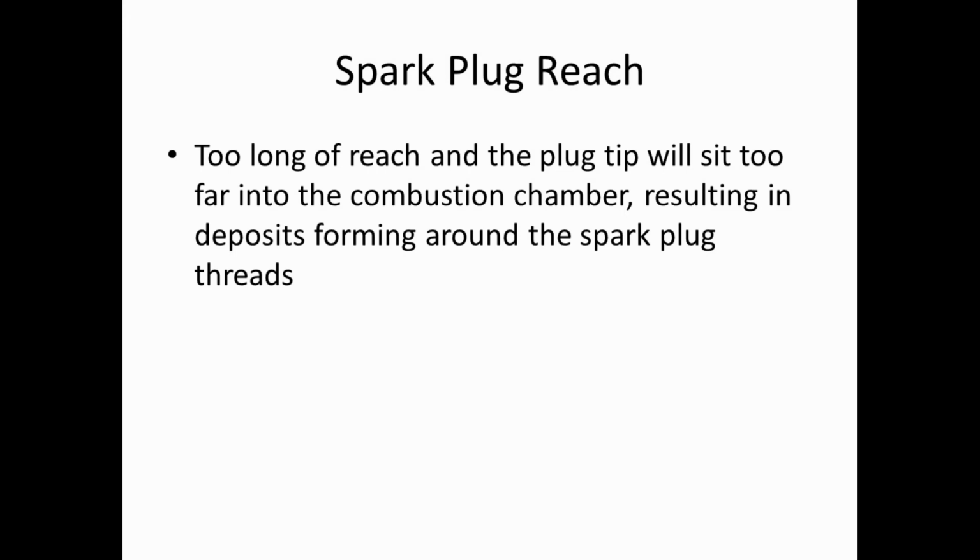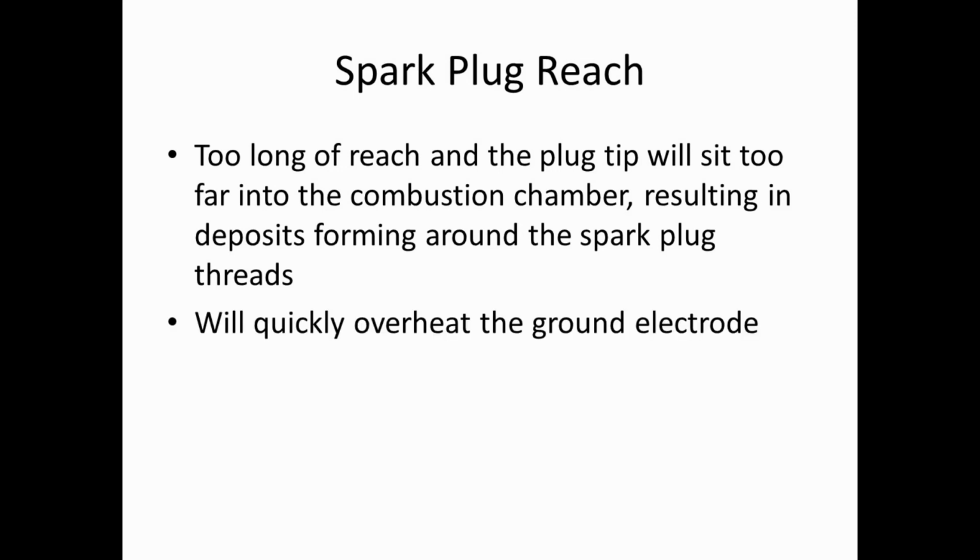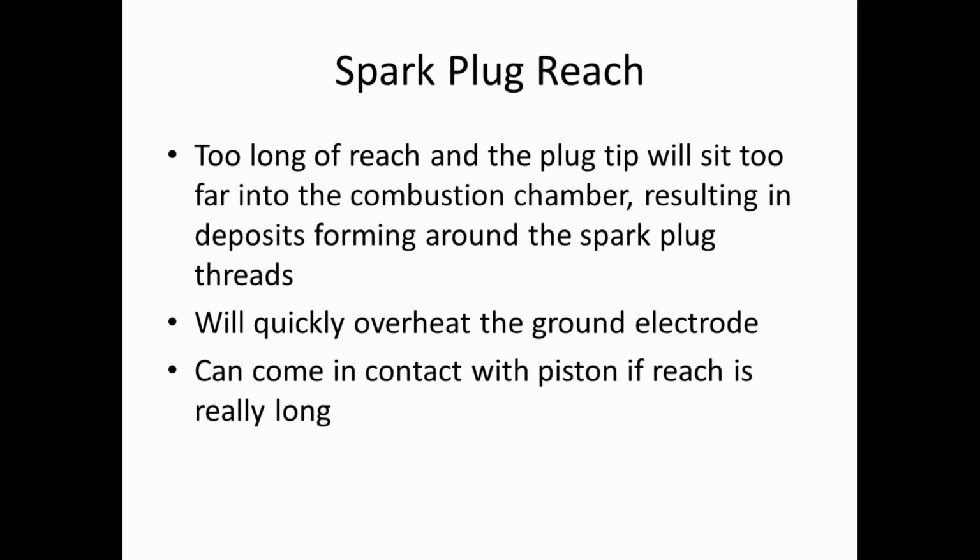Too long of a reach and the spark plug tip will sit really far into the combustion chamber, and you'll have deposits forming around the threads if the engine happens to run long enough for that to happen. Because the threads sit too far out, there's nothing for it to conduct the heat into the surrounding area. So your ground electrode will overheat very quickly and most likely melt. And what will most likely happen if your reach is too long is it will come in contact with the